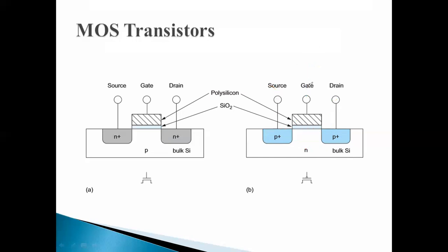Now let us consider that the gate input of this PMOS transistor is supplied with a negative voltage. So when negative gate voltage is applied to the gate terminal of a PMOS transistor, because of the law of charges, like charges will repel, whereas unlike charges will attract. So because negative gate voltage is applied, positive holes get settled just beneath the gate layer.